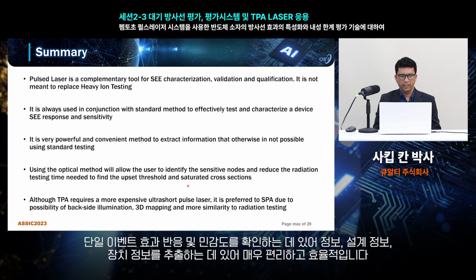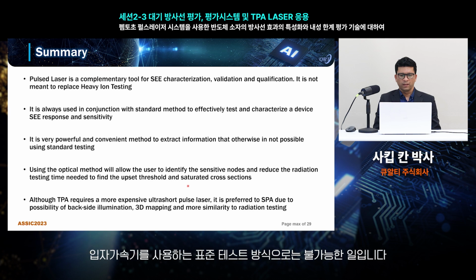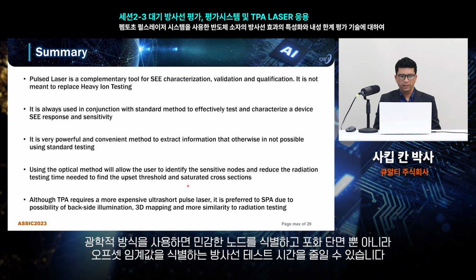It is a very powerful and convenient method to extract design information and device information that is otherwise not possible with the particle accelerator standard testing. Using the optical method, it allows us to identify the sensitive nodes and reduce the radiation testing time needed to find the upset threshold as well as the saturation cross-section.